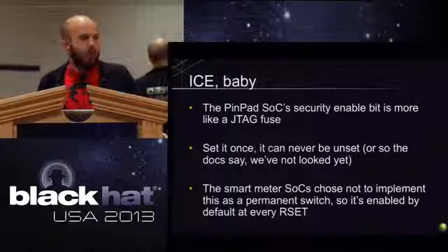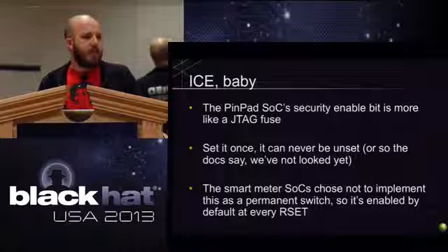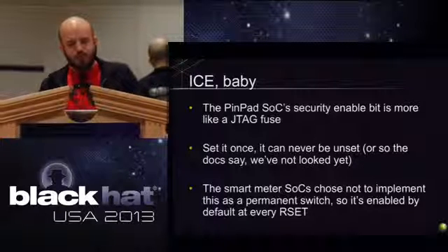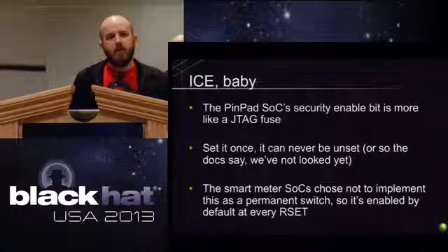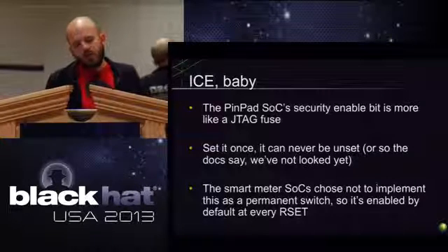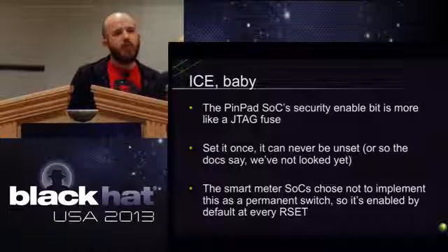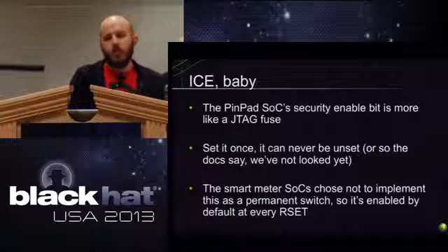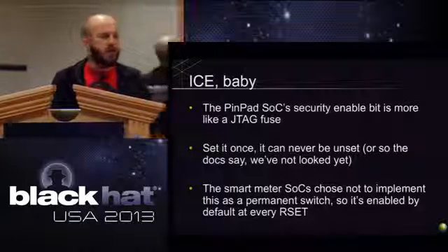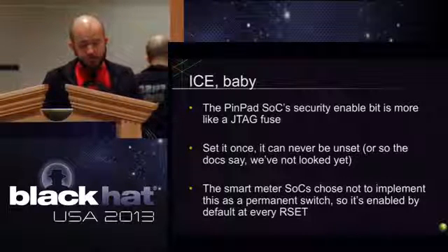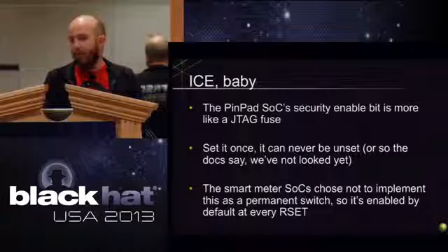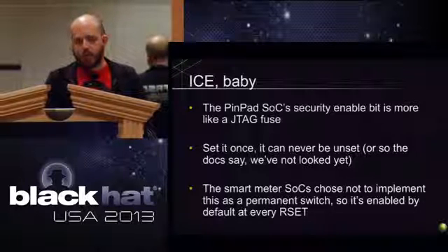The pin pad ones are a little bit different. They allow you to permanently set that bit that says keep this thing off, but this one doesn't. So pin pad one is more like a JTAG fuse. We've not actually looked at one of those, so I don't know how robust that is, or whether you can use similar types of attacks that have been used on JTAG fuses to get back into it, but the documentation says that it's permanent. Smart meter SoCs chose not to do that, so there are certain security ramifications to that.